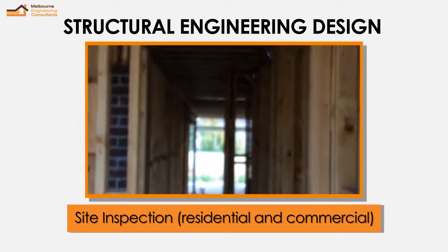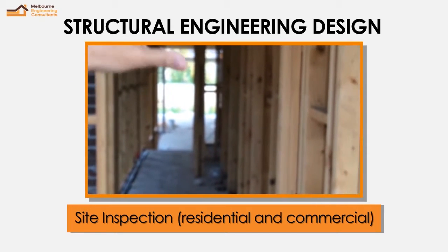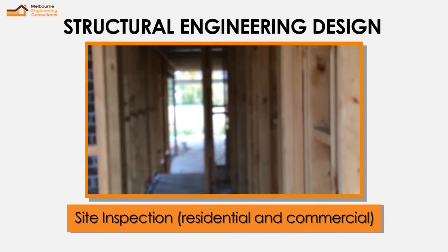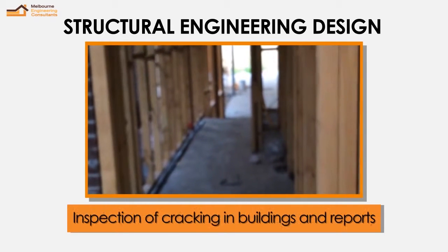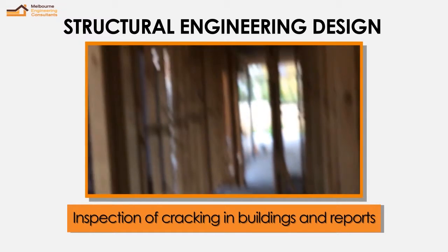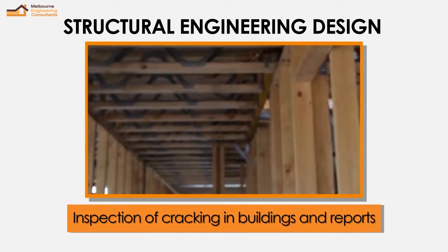Internal walls in here are non-load bearing, so we don't need any lintels inside, only the outside are the load bearing walls. Most of the first floor structure is sitting on my steel beams or timber beams.